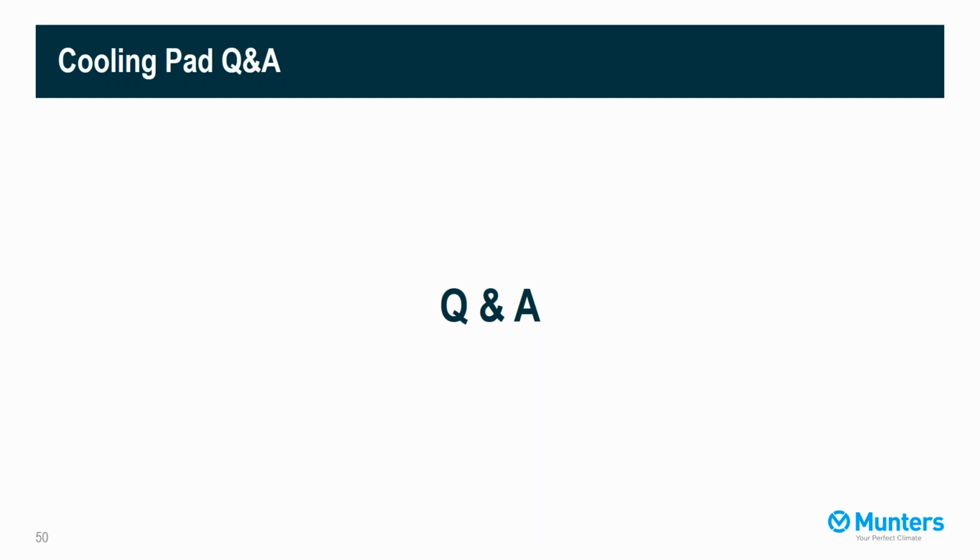We'll take one more here, and then it's, can the cooling pad flute angles be altered to match the cooling demand depending on the ratio of sensible and latent load present? How does that work? There are manufacturers of pad that have different angles of pad. For our purposes, we use the 4515 pad, as Dave mentioned.